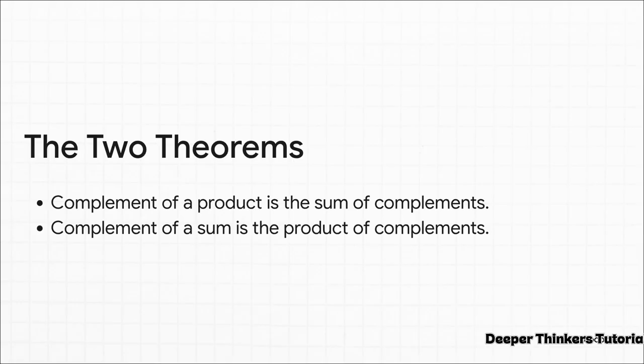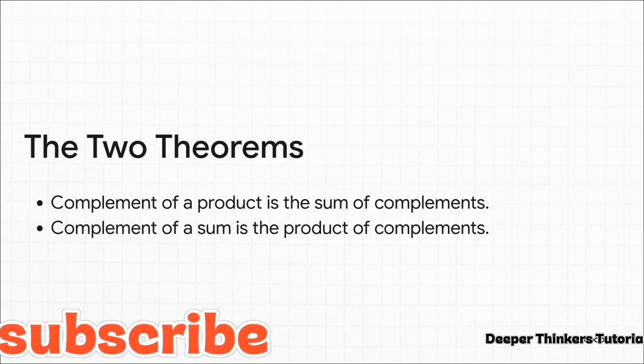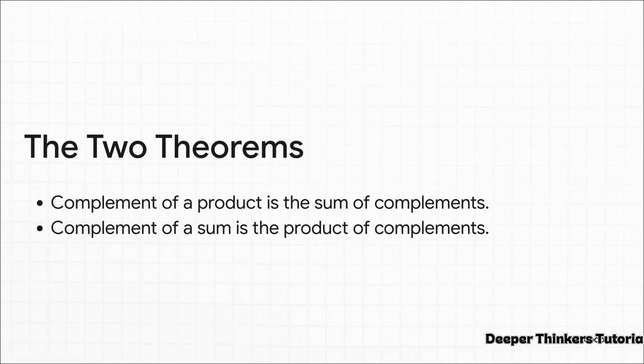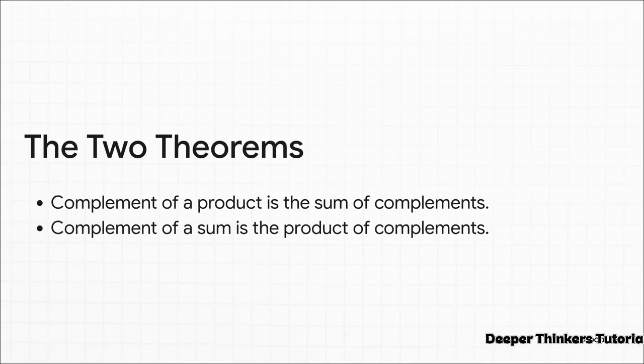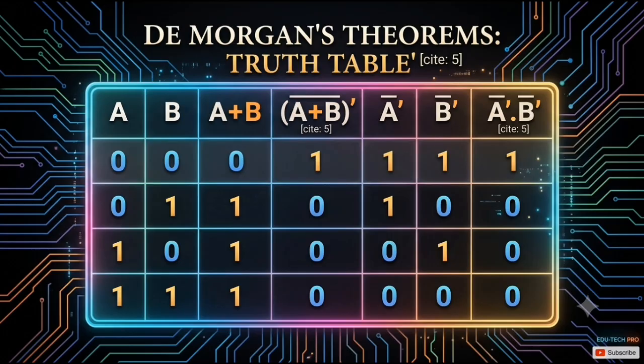It's equal to you taking A complement only, then dot B complement. So it's just like an inverse. If it is multiplication, that's dot, and you have a long complement, it will be equal to each of the individual complements, but now you are having a plus, which is OR. But if it is a plus that you have a long complement on, it will not be equal to you taking the individual complement, but in this case it will be a dot, which is an AND.